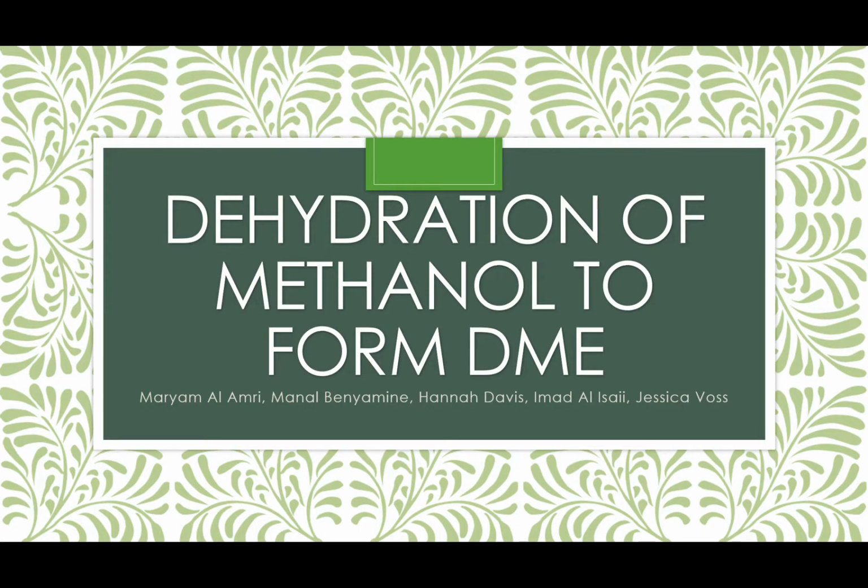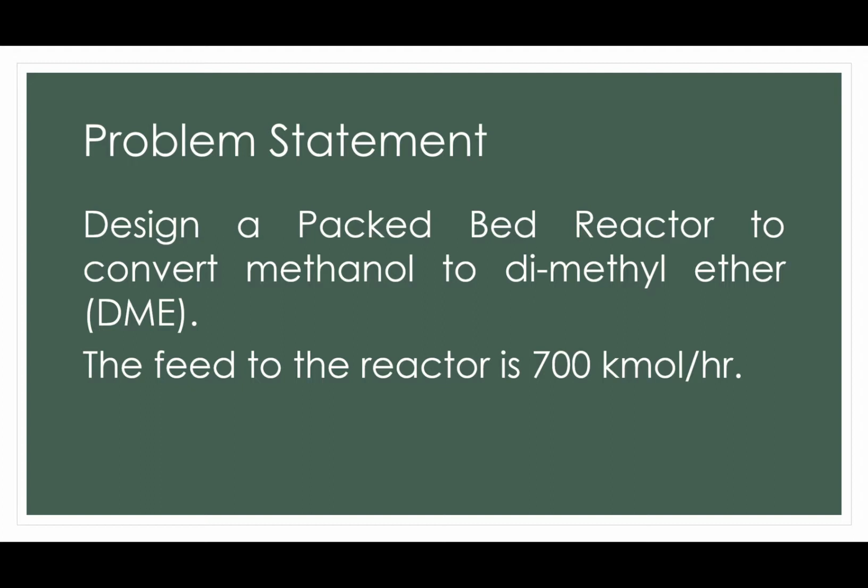Hi, today I will be talking about the dehydration of methanol to form dimethyl ether. The problem we are approaching is designing a packed bed reactor to do this reaction. The dimethyl ether will be converted from methanol and the side product will be water. The feed to the reactor is going to be 700 kmols per hour of a not completely methanol feed. The other portion of it is water.